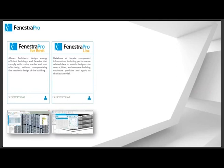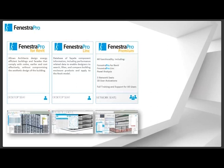FenestraPro Link offers that database of facade components, mainly glass, showing a lot of the leading manufacturers' products, but also more generic glass types that you can filter down and search for glass type, and search for a material that achieves these parameters, and assign that to your Revit model, and thereby update the properties and see the implications of those decisions.